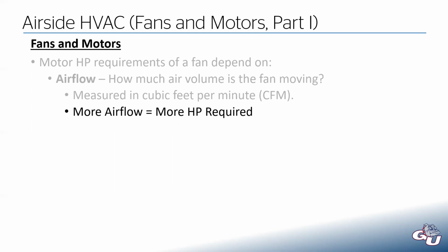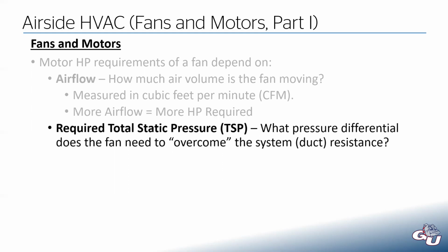Another major component of this is the total static pressure. And that is, what's the pressure differential across that fan that's going to be needed to overcome that system resistance?